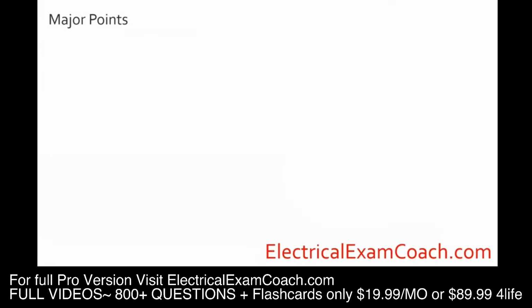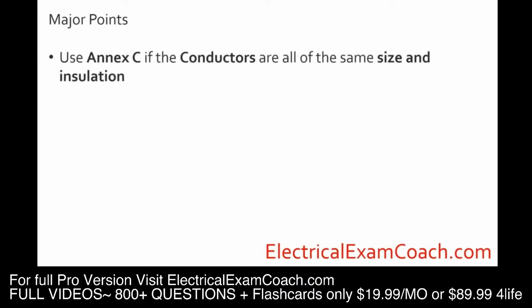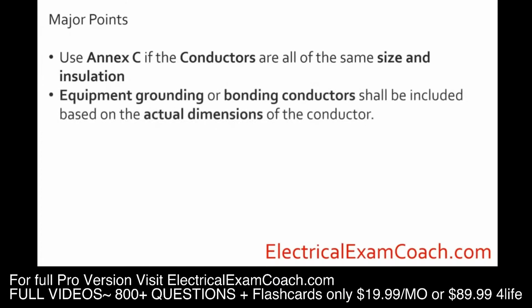Before we jump into the practice questions, let's go ahead and hit the major points. We're going to use Annex C when all of the conductors are of the same size and insulation. When dealing with equipment grounding and bonding conductors, they shall be included based off the actual dimensions of the conductor. It's not like we did in box fill. If there is a grounding conductor in that pipe, it counts 1 for 1, and all of them count. If you've got 10 of them, they all count.